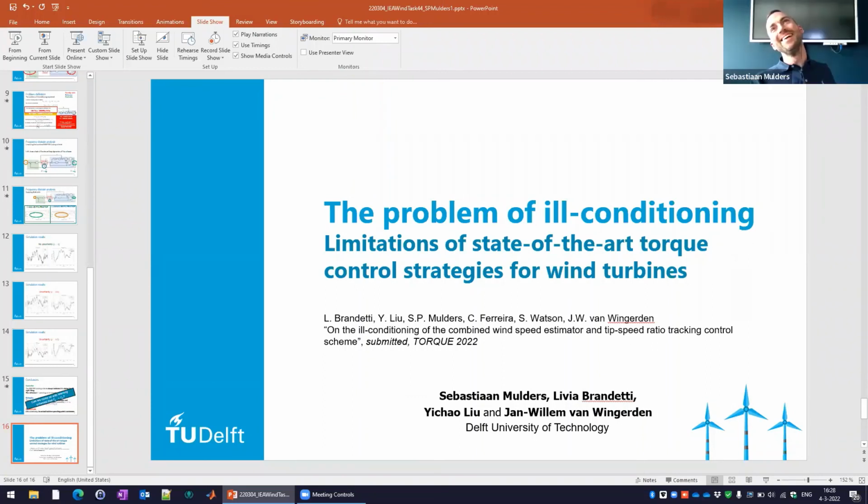Good question. I'm mostly looking at wind turbine control, of course, but I think that each wind turbine should be able to possess accurate CP tables of its own, because what I see in certain papers is that wind turbines in wind farms are used as sensors. So each wind turbine has its own wind speed estimator, and that information is then fused, or sensor fusion, maybe in a big estimator used in an observer to make a prediction of the whole wind speed in a complete wind farm.